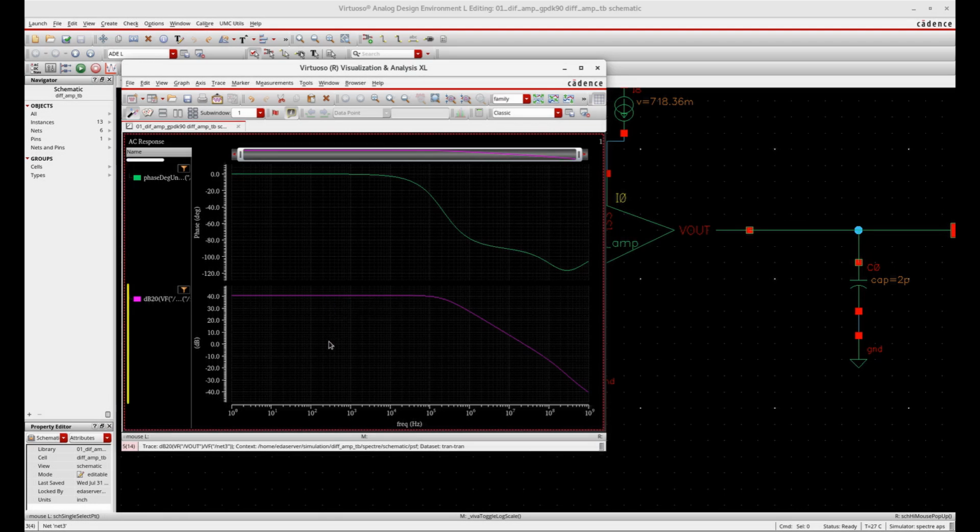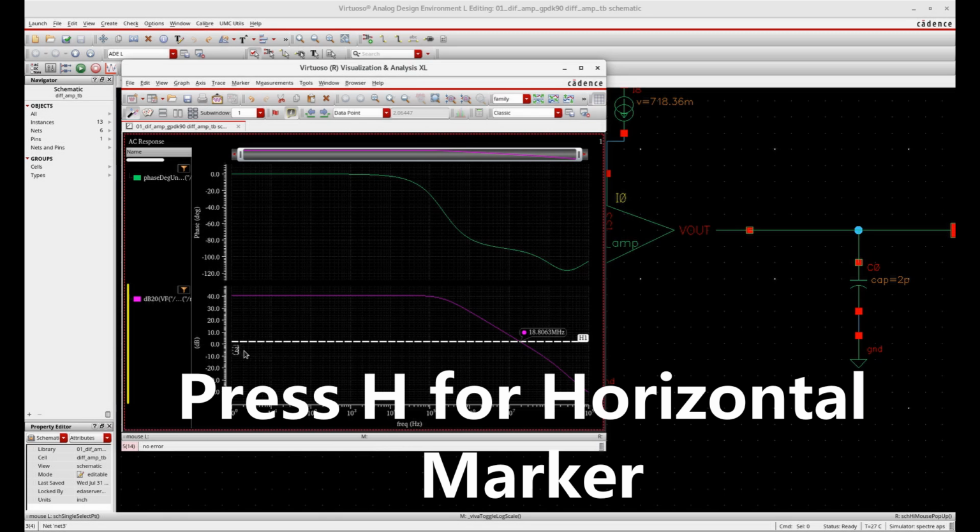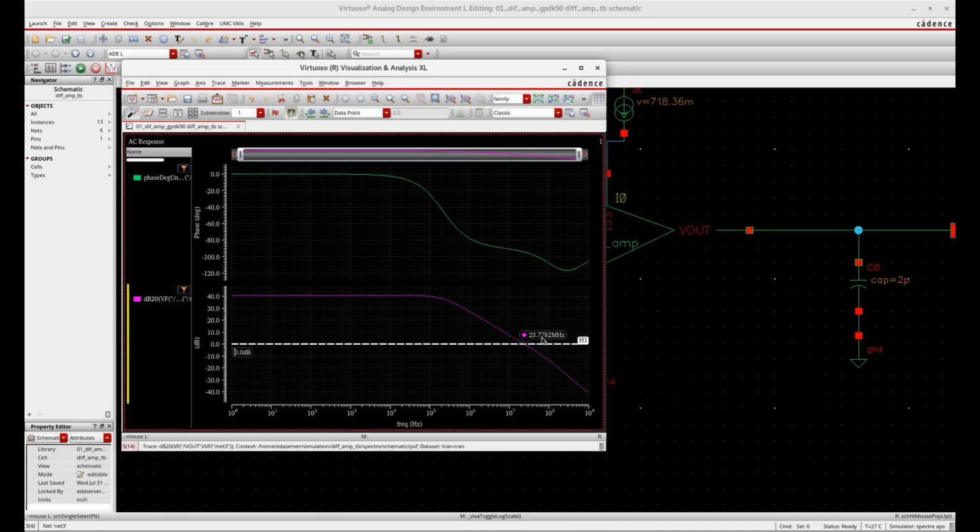And check the GBW, 23.77, less than equal to 30 megahertz, so it's maintaining. If you want to increase the GBW, then you have to tune the input pair W to increase the width of the input pair. Then GM will be increased, accordingly GBW will be increased up to 30 megahertz. So it is a matter of tuning.